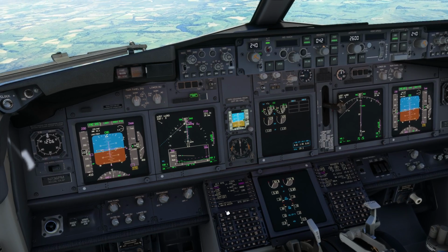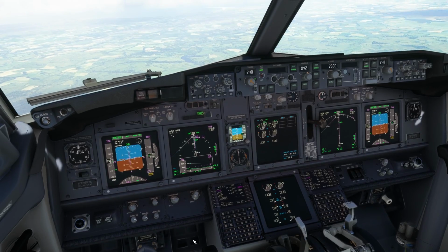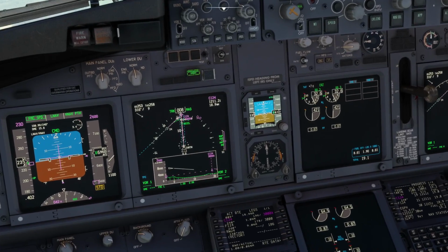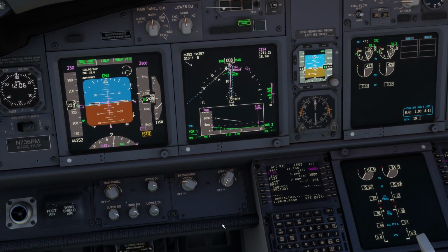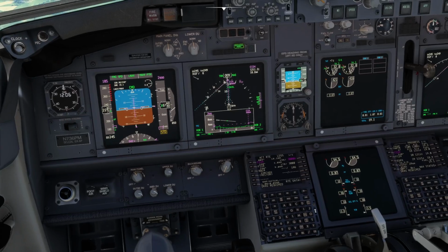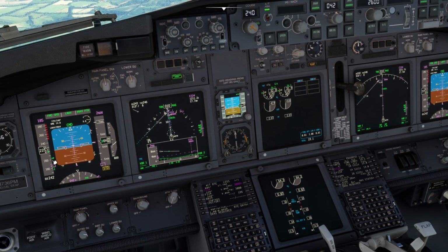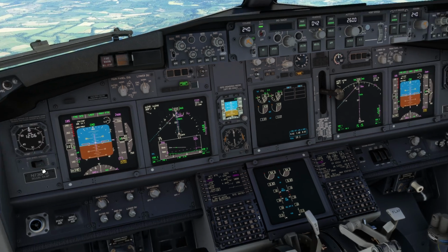So it's saying here drag required. So it lifted the nose, and we've obviously got the spoilers out already, so it will actually tell you if it can't do what it's being asked. So we'll go for first stage of flaps. You can see that they introduce a new airspeed limit to the aircraft. You can see there's an up sign here. Once we go past that, we can actually drop the gear.